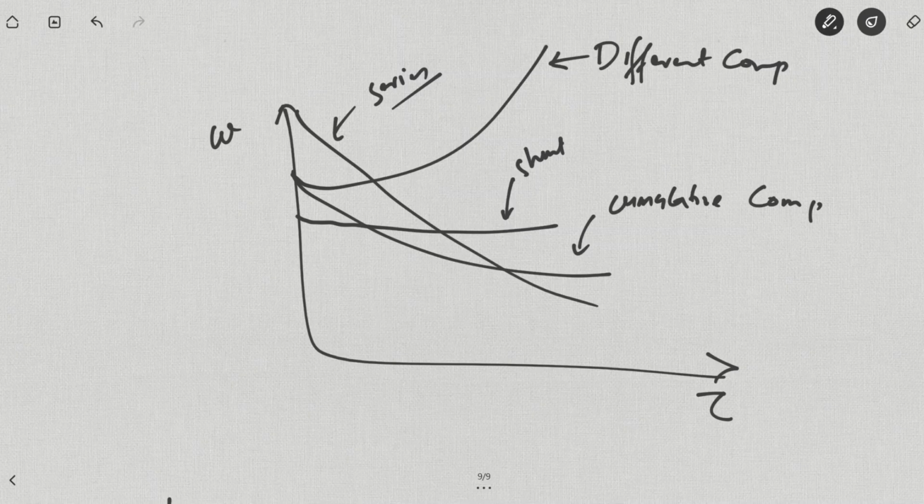A cumulatively compounded DC motor basically takes up the advantage of both shunt and series DC motors and removes their limitations. So it has a torque speed characteristic that lies somewhere in between the shunt and series DC motor. As far as a differentially compounded DC motor goes, the flux always tries to approach zero as the motor is loaded more and more.